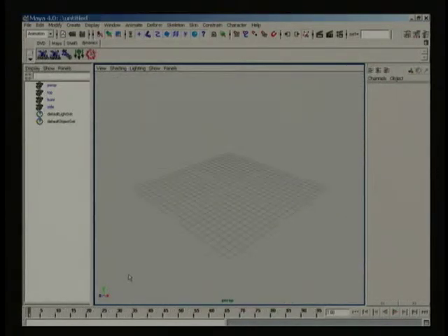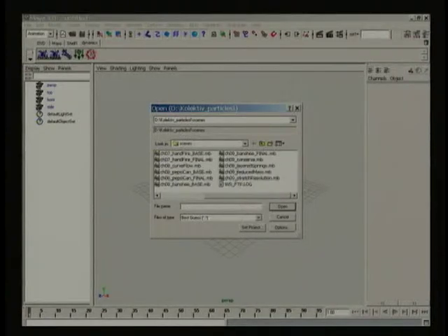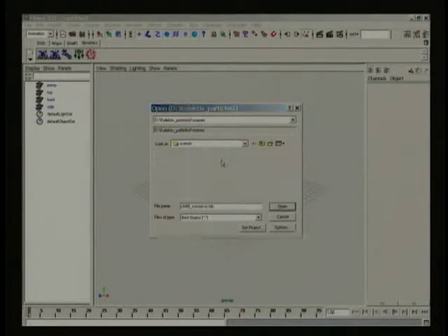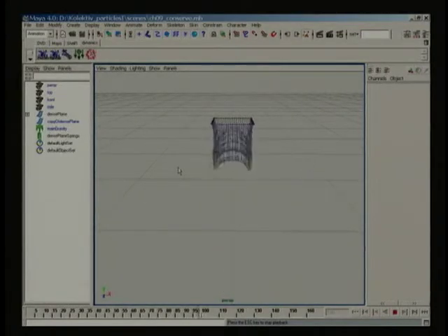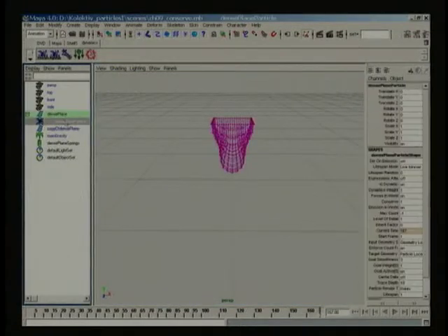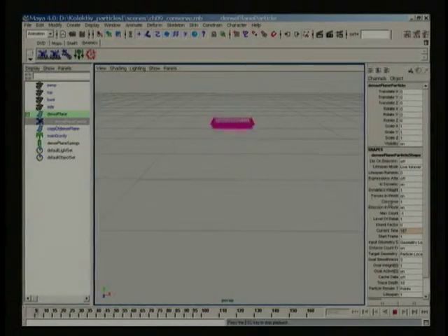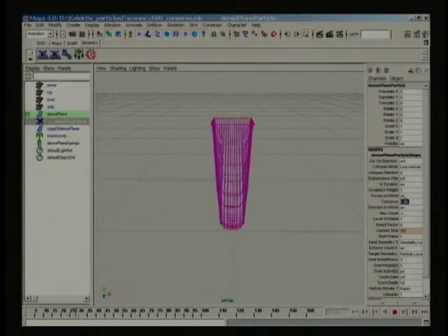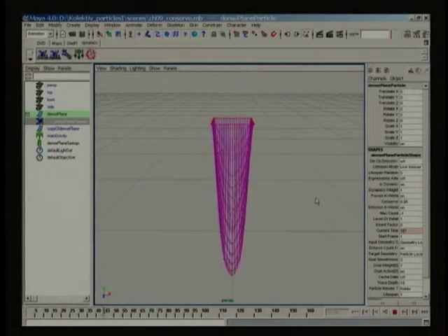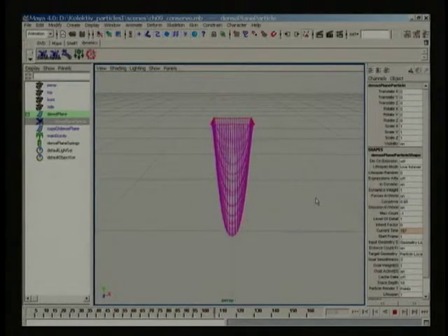The generally accepted method for decreasing the amount of stretching in softbody simulations is to add springs and increase goal weight. Before applying either of these techniques, try reducing the conserve attribute on your particles to a value less than 1. Conserve is the amount of velocity your particles carry from one frame to the next. In the real world, there is always some sort of resistance to take into account, even in the vacuum of space, where gravitational pull from distant objects must be taken into consideration.